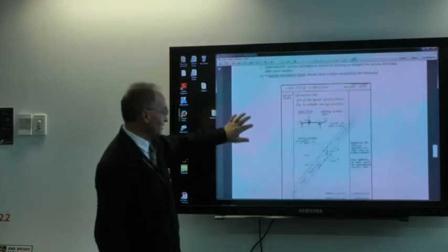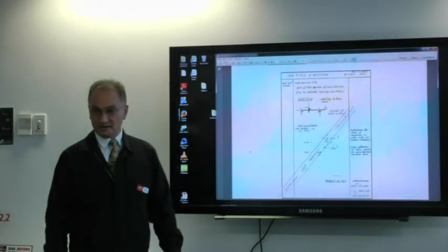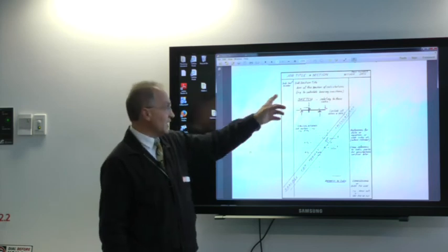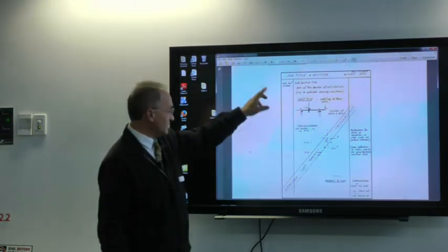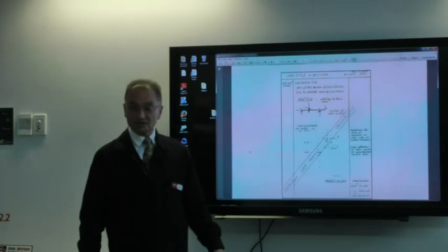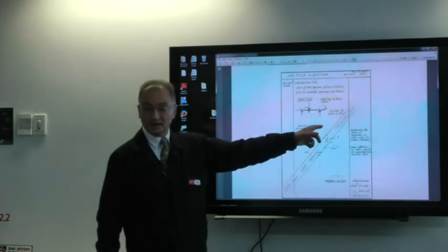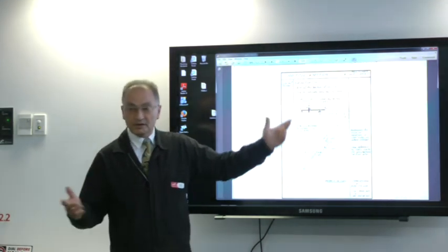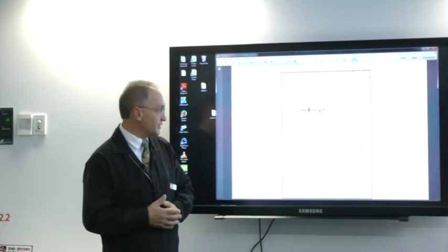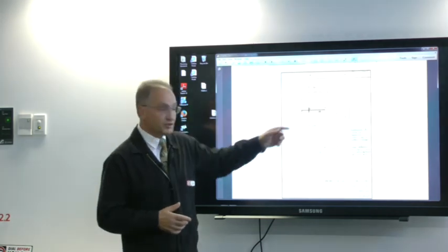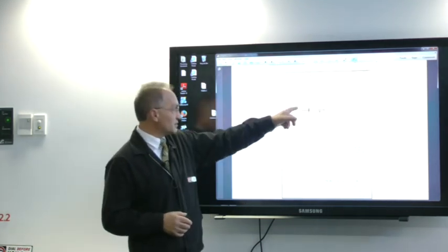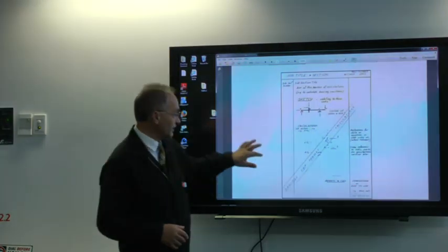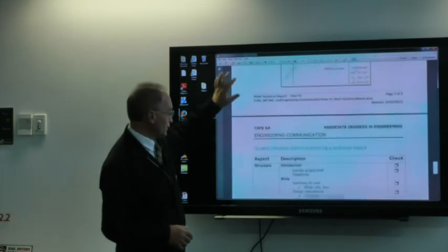And the way calculations should look is a little bit like this. You have your grid paper, you have your heading and subheading and author and page number, and usually there are two columns on the side where you either write the standard reference, like could be AS 3600 clause 3.4, for example, if it's concrete design that you're doing, a diagram showing the data that you're using in your calc, that's representing a beam with forces on it, and the calculations with underlining of the main points.